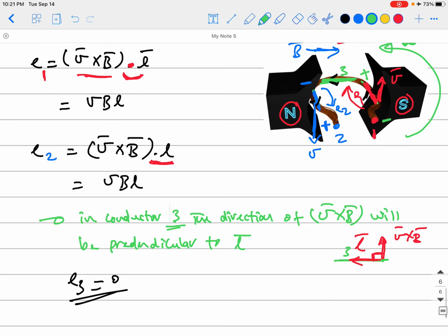So there is no induced voltage in it, and we don't need it. Okay, so if you can get rid of it, just get rid of it, but actually we cannot, because we need to connect the two conductors 1 and 2 together, and we don't have any other means but to connect them by this piece of wire, which most of the time does not have any induced voltage in it. So that's why we call it the overhang or the end winding, because it's something we use to end our winding, to connect our two pieces of conductors 1 and 2 together.